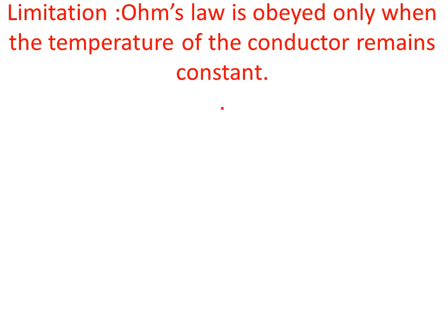In case of changing resistance, we can find resistance at various points, and that is dynamic resistance. Resistance is also changing, not constant. But the method to find resistance is as usual: delta V upon delta I is equal to R, resistance R, that is, the slope of the voltage current curve gives us resistance.